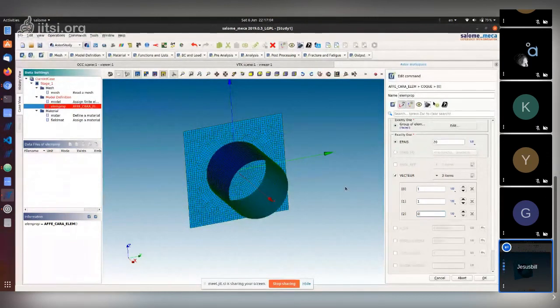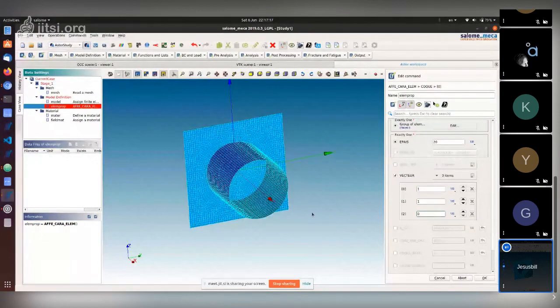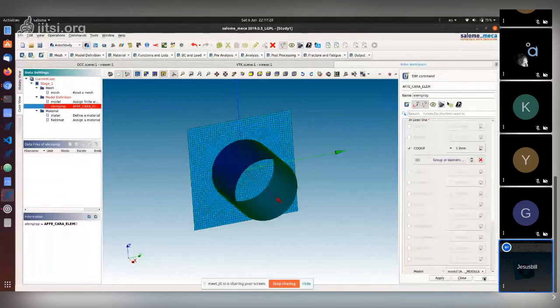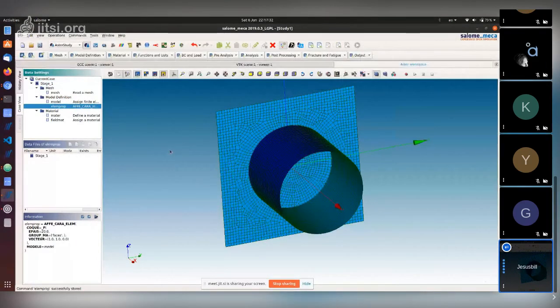So when you are looking also for the forces or the stresses that have reference in local axis, you know where this local axis x is. If you don't define it, then it's going to be by default along the x-axis, but it should not be perpendicular to any face. So in this case, for the plate, it will give us an error, so we have to assign it. And by doing that, we have also the element.